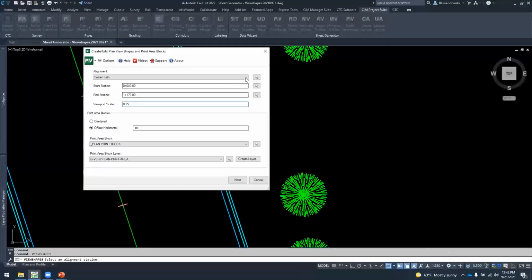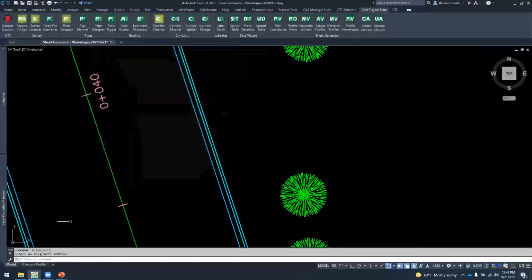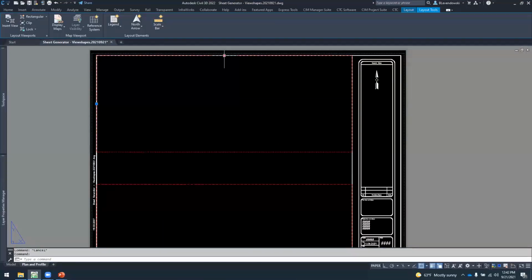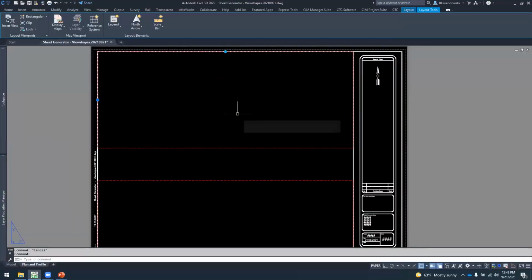And so what is this? What's going to help you understand this a lot better is if I click right over to my standard sheet template. This is basically an empty template with just some of the out-of-the-box stuff from Autodesk, right? But you would use your custom sheet template. And what I have in here are two simple AutoCAD blocks with an insertion point over here. And for convenience, I put a little rotation parameter in mine as well. It's a simple polyline turned into a block.